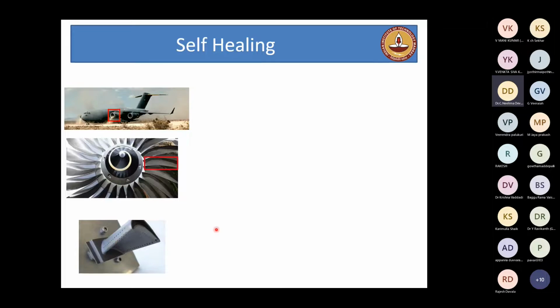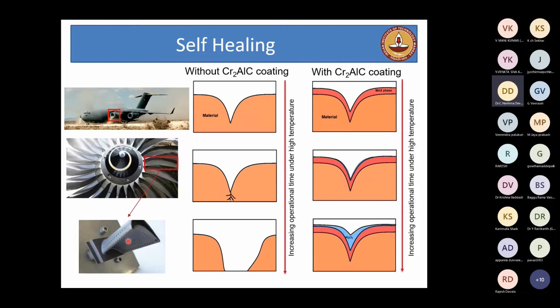Now, imagine a condition where you do not have any coating but the raw blade is being exposed. This means a crack can initiate on the surface and it can propagate continuously, because there is no arresting mechanism for the crack propagation, because this propeller blade is rotating all the time.